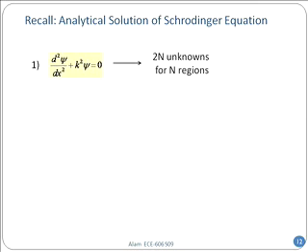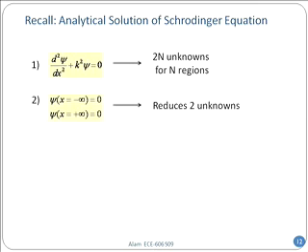For example, remember that when we had analytical solutions, we had the second order equation, and in each section, we solved them individually, right? We solved A sine kx plus B cosine kx, or the exponential form. We had these individual solutions in various places. What was the next thing we did? We had the boundary condition on the 2 sides. These are the metal contacts. And in this problem, these are metal contacts on 2 sides, and that is sort of the plus infinity, minus infinity equivalent to the boundary condition.